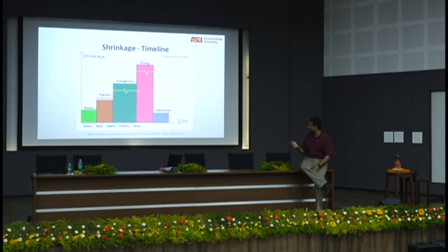So, if you look at different time scales, you have plastic shrinkage that happens very early, you have thermal shrinkage and contraction that happens days to weeks, autogenous shrinkage actually happens right all the way here, and then drying shrinkage happens later. Carbonation, I mean, this is not exactly the timeline, but just to show sequentially when this happens. And then you have carbonation shrinkage also.